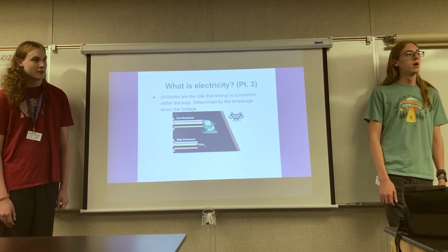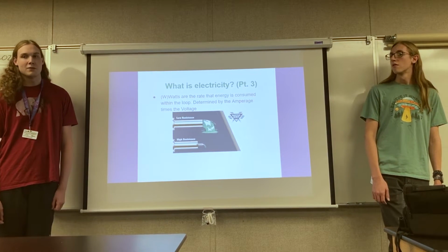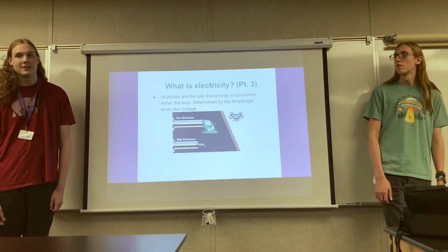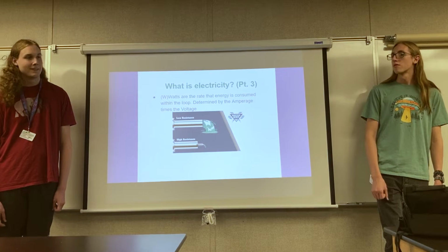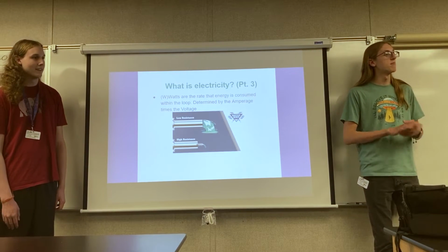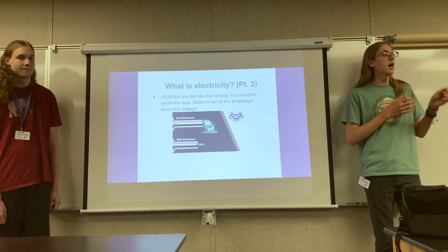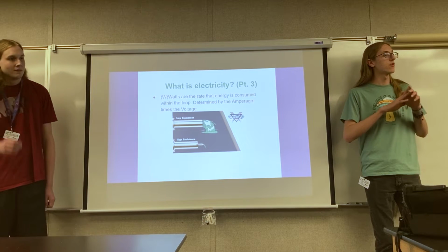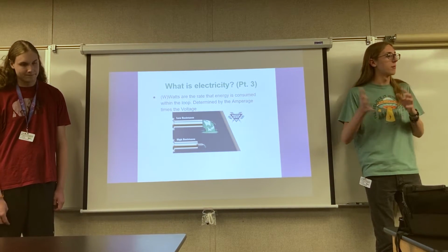And how much voltage are we going to be using? Our robot uses 12 volts and 5 volts. 5 volts for the brains of the robot, the roboRIO, and 12 volts for all the other systems. The 12 volt electronics are the ones that are not as regulated. Those are our motors and things like that, where we're taking the power straight from the battery.